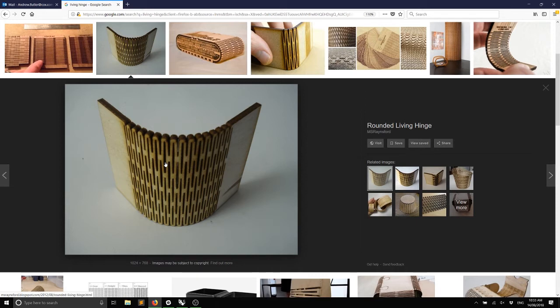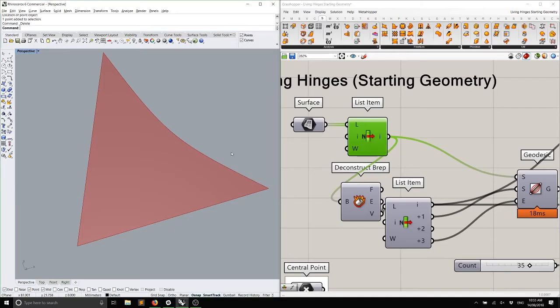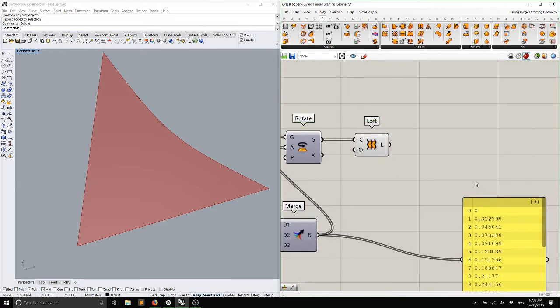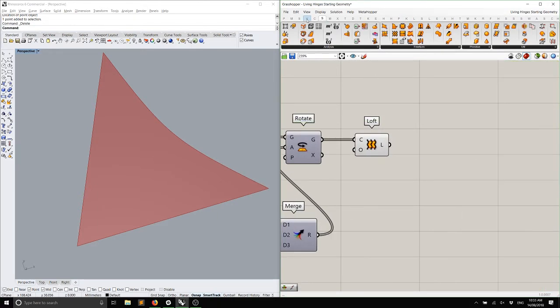Cool? So just as a quick process, as we work on this, we got to get our surface to look like that. We're going to use this thing called isotrim. What it does is it takes a domain, a two-dimensional domain, and applies it to the surface.